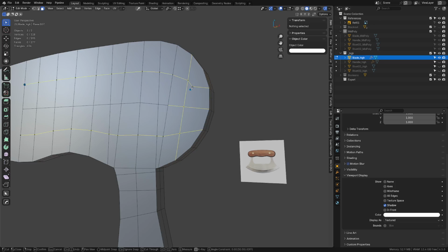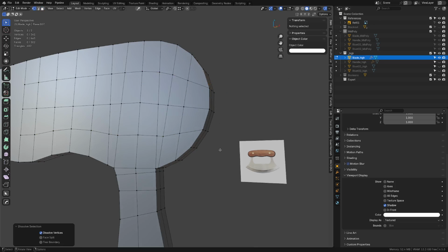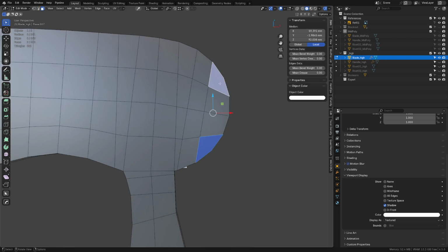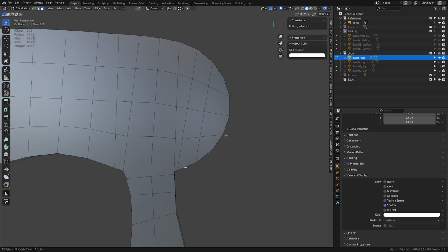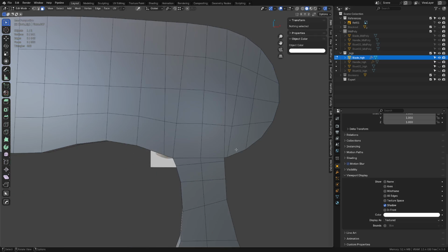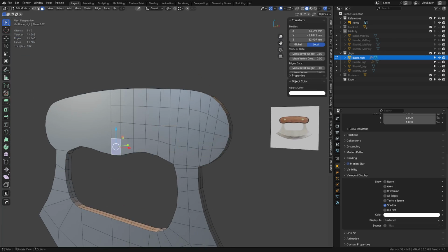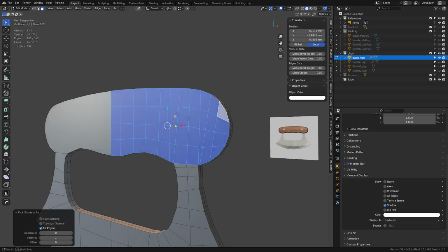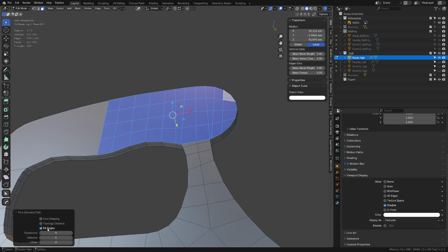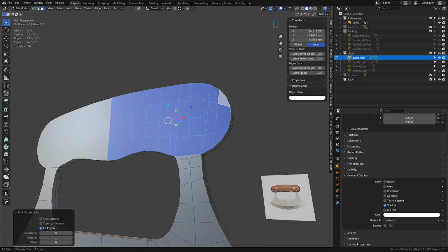You can see I created an extra vert by accident. Dissolve it, boom. All right, but now those quads are out here and they got 2 in the middle. It just works out a little bit nicer. So we can do that. If you want to balance this even more, what we can do is Control Shift click through here. We can now do a shortest path selection with fill region. Quads work well with that.